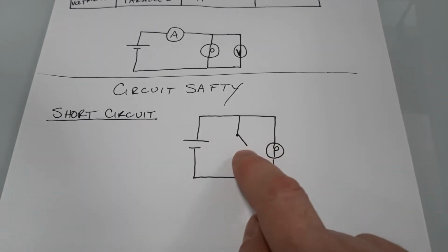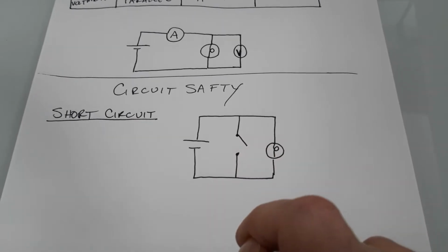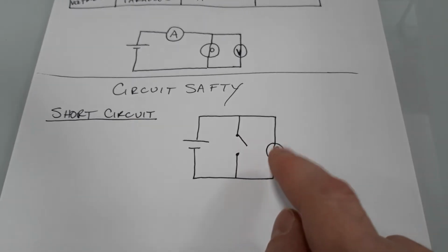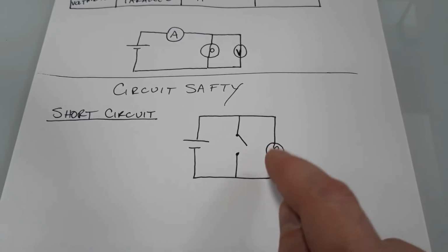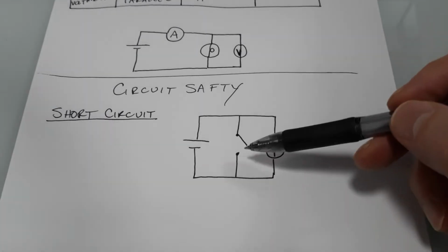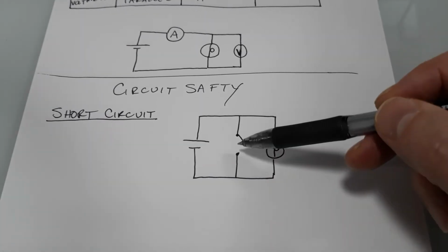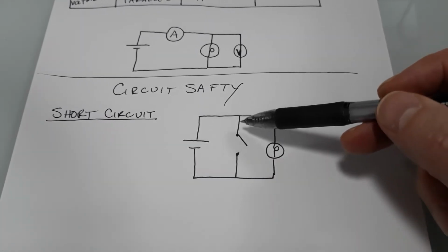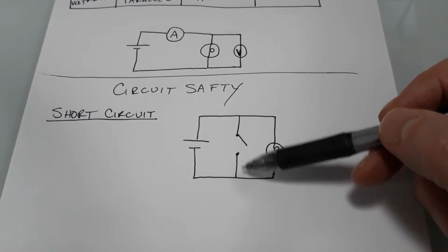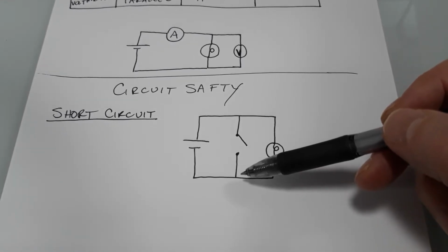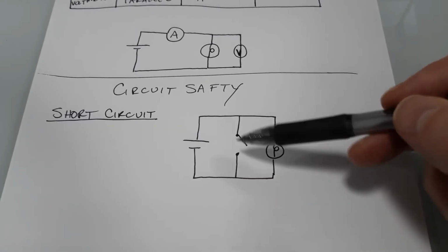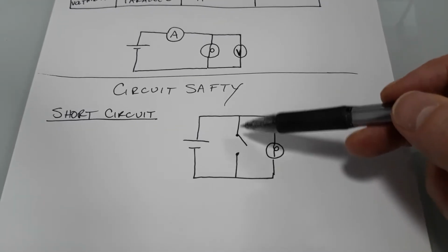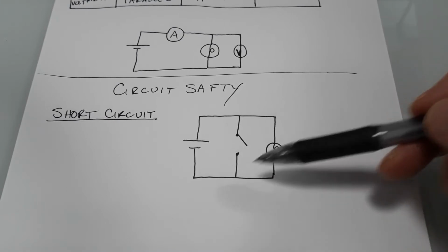Now, as soon as I close this switch, the bulb's going to turn off. It will not produce any light anymore. And it's not because it's not getting any current, but it's going to get very, very little current. Because as soon as I close that switch, I will have created a second branch which has basically no resistance. There's virtually no resistance. So imagine this had a resistance of 100 and this had a resistance of 1. Well, this guy would then get 100 times more current than the other guy.